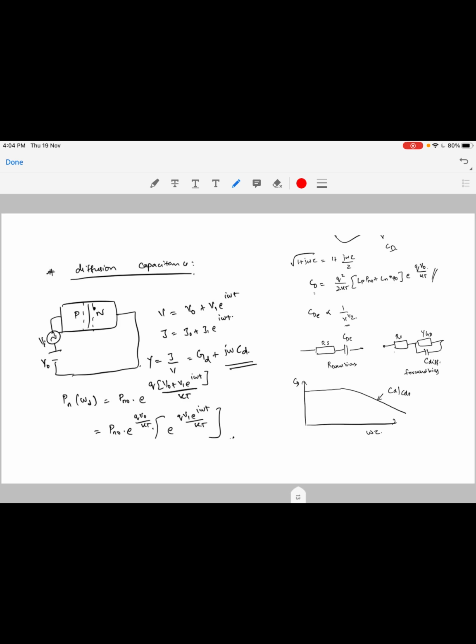In reverse bias, you have what is called the depletion capacitance, which dominates. When you have a forward bias, you have a capacitance due to the minority carrier concentration not responding as fast as we want, hence giving you a capacitance called the diffusion capacitance. We derived an expression for diffusion capacitance, and it is this diffusion capacitance which dominates in forward bias. So you have an effective model of a diode in reverse bias and a model of a diode in forward bias in this particular format.